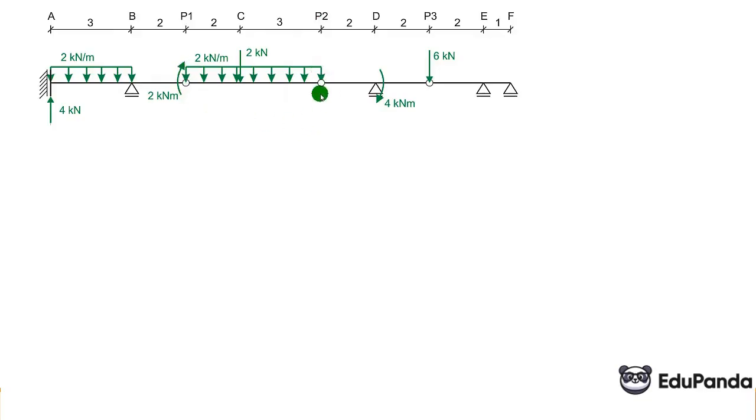And let's also look at the beam AP1. Here we have a moment, a horizontal reaction, one vertical reaction, and a second vertical reaction from the joint, which is also not calculable. Because there are two vertical reactions and a moment. And we remember from the previous slide, you can have either two vertical reactions and a horizontal, or a moment, horizontal, vertical. And here there is a moment, horizontal, vertical, and yet another vertical. So this is an immediately non-calculable beam.